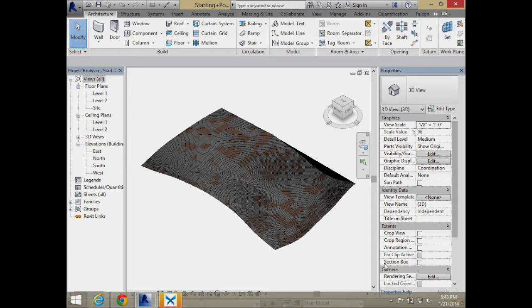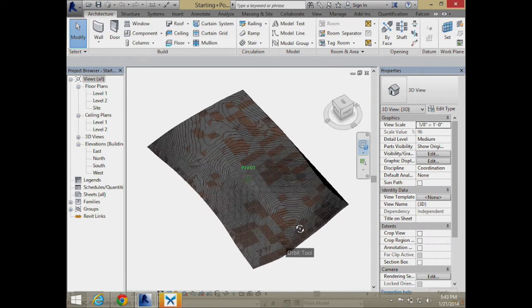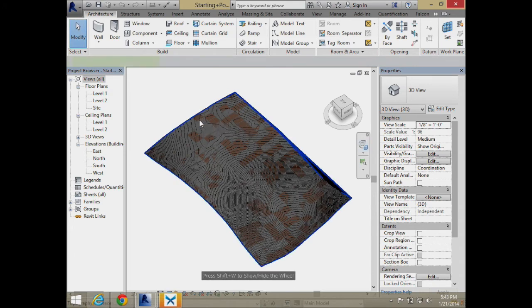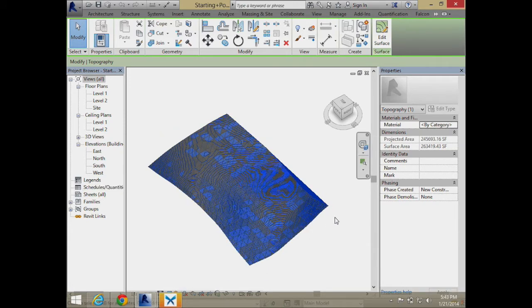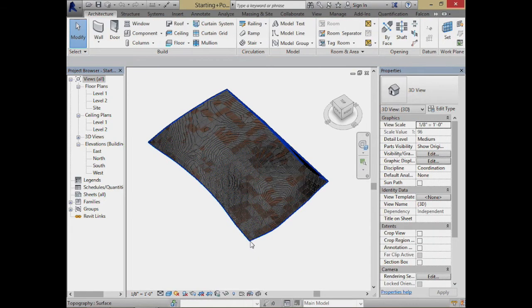Okay, here is the site that has been pulled together for you guys, just so everyone understands where this site came from. How did you generate this site? Oh, well, I put it in from Google Earth. You can put it in using SketchUp from Google Earth and transfer it into Revit. For the Jasper site, just get the coordinates and then you put it in. Excellent. So there are two different things here. There is a DWG file, which holds the coordinates and the actual elevations and all that information. That got pulled in from Google Earth, and from that we were able to generate this topo surface.